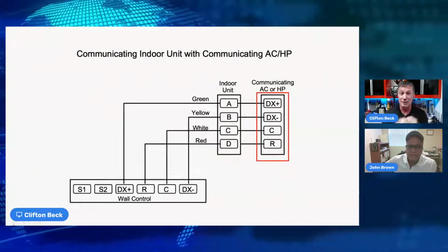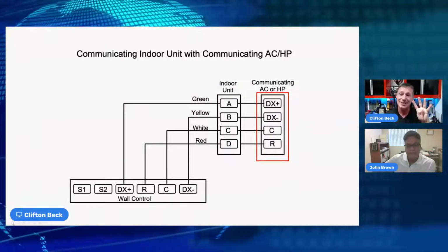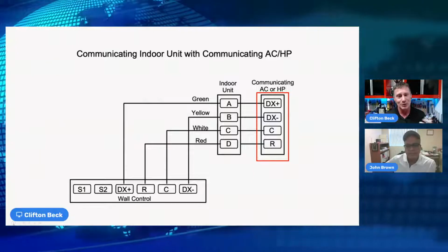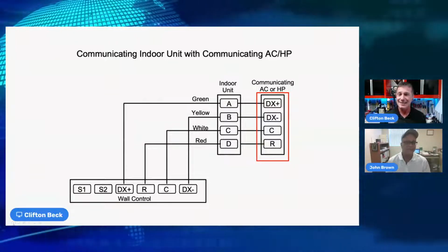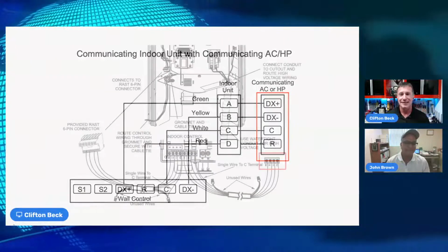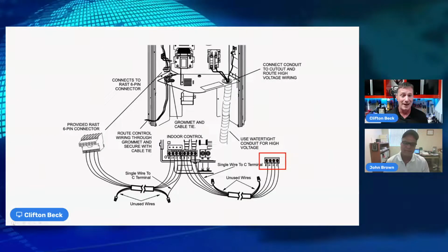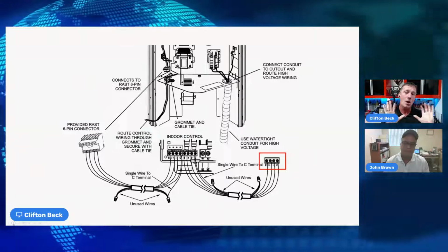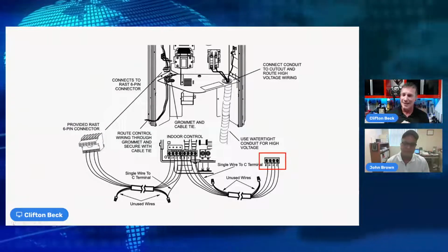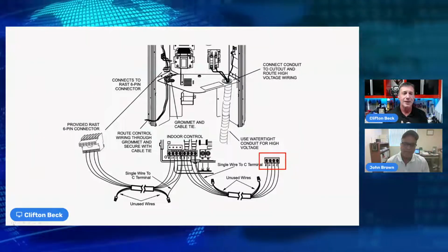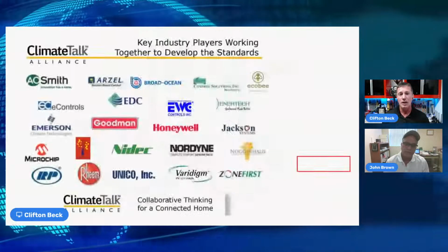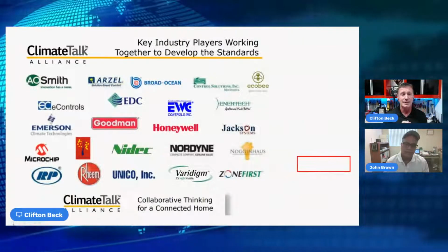If we look at this one, we're going to see a 4-wire connection. 2 of those are 24 volts AC, and 2 of those are labeled as a positive DC and a negative DC. So we look at this manufacturer, another reference of the exact same thing. I'm not saying that all manufacturers use the exact same, because I have seen some variations of it, but I will say that the philosophy, the technology behind it all comes from a similar design.